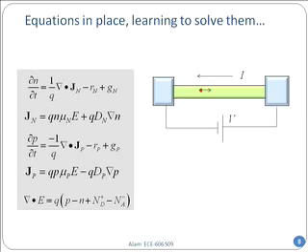We know drift and diffusion equations. We know the continuity equation we just derived. Now, if you have to solve it, now there would be a problem. Do you see why there might be a problem? First of all, how many unknowns do I have here, do you think? I have 3 unknowns. Do you see? Electron number, hole number, and the electric field or potential.